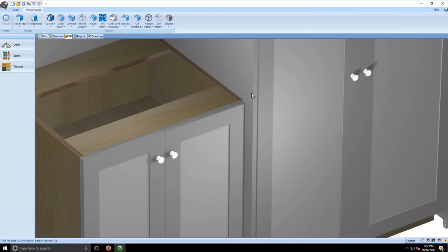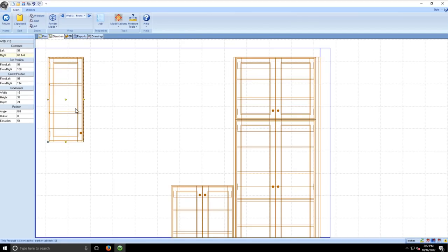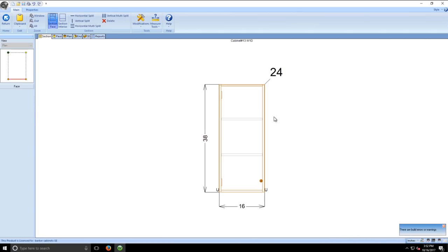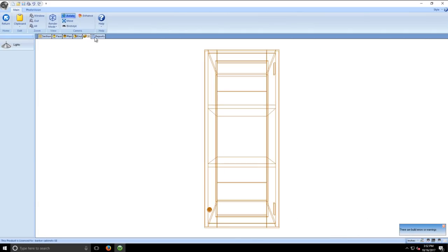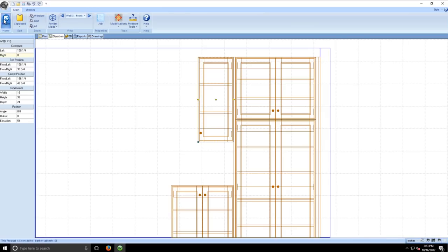So order your tall cabinets at 26 inches deep. Order your tall in panels 26 and 5/8, and then have the countertop run into the side of it. I think it looks way better. I see that in displays sometimes, and it's like, ugh. All right. So anyway, that's how the base cabinets operate there. Same thing with the wall cabinets. You want the wall cabinets to go over here. Again, clearance. We're just going to go 0.